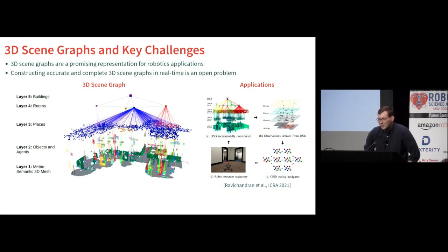However, previous approaches like Chimera, scene graph fusion, and others have had to make trade-offs between scene graph completeness, online operation, and actually correcting the scene graph for noise during scene graph construction. Chimera especially could take up to 30 minutes to construct a scene graph for large environments due to a reliance both on a global voxelized ESDF of the environment, as well as a need to rebuild the scene graph from scratch to actually correct for drift after detecting a loop closure, both of which aren't great if you want to use scene graphs for real-time robotics applications.